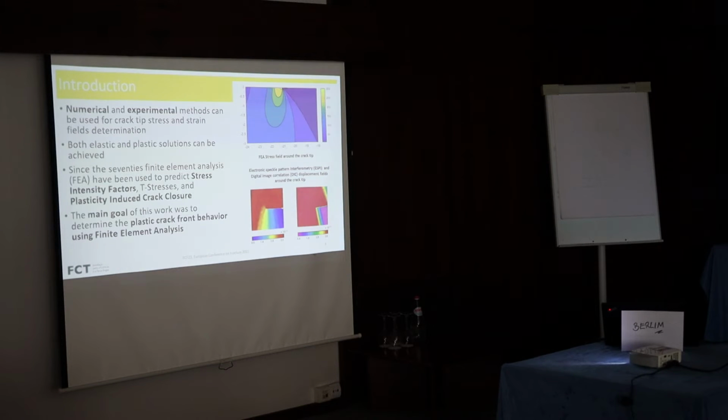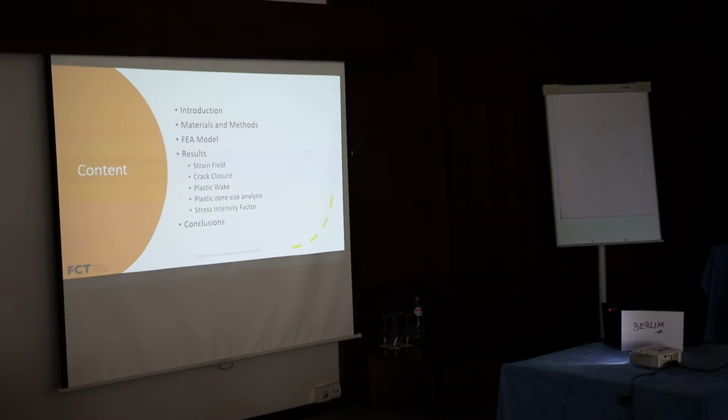In this study, we use both the stress intensity factor and the plasticity induced crack closure. The main goal of the study was to determine the plastic crack behavior using finite element analysis. In this case, it was the Abaqus program.